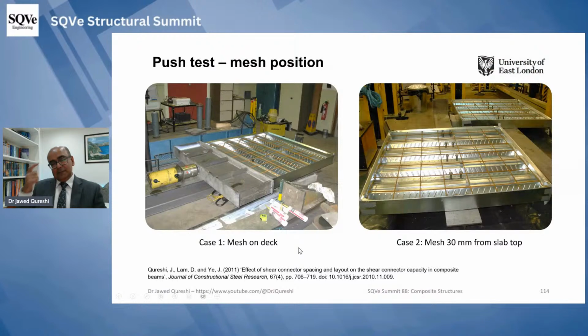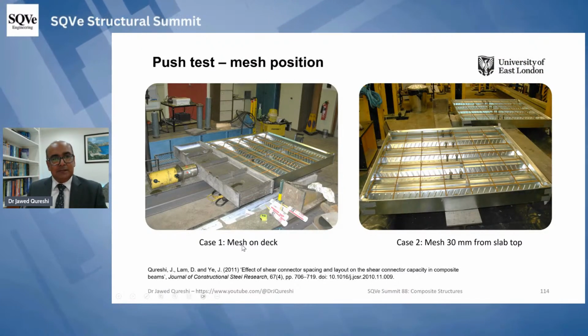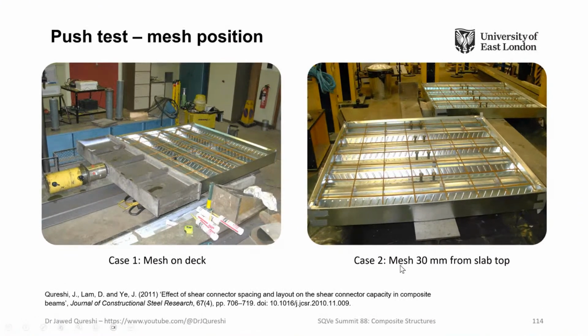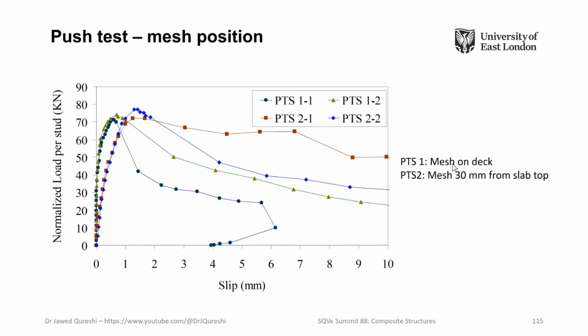So this is the testing that I did as part of my PhD at University of Leeds. One is mesh on deck, directly on deck. Another is mesh which is 30 millimeter from slab top. So here you can see that we use these small chairs over here so that the mesh is raised. And this was the testing results. PTS1 is mesh on deck, PTS2 is mesh 30 millimeter from slab top.